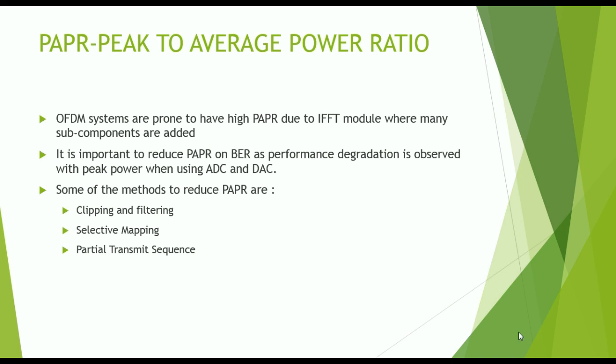This results in intermodulation among subcarriers and causes interference in the system, which reflects in the form of a high BER because of the high PAPR seen in OFDM systems. So it becomes necessary to lower the PAPR of the transmitted signal to maintain low BER. Thereby, it means that the interference has to be reduced.